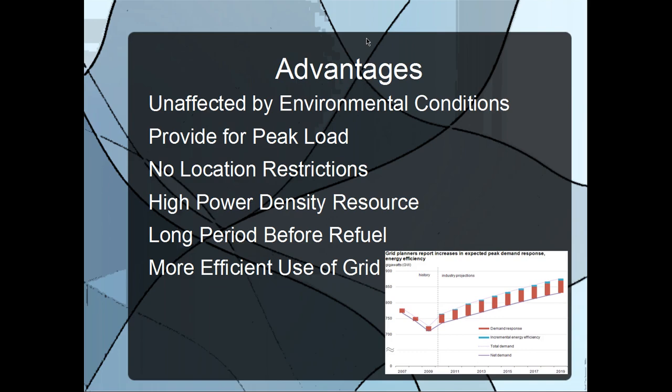Coal and natural gas plants need to be located near a primary source or have extensive support to provide continuous fueling. This is necessary due to the low electrical production value of coal and natural gas. For example, it takes about 1.05 pounds of coal to produce just 1 kilowatt hour of electrical power, and 1,000 cubic feet of natural gas to do the same. This means that the typical 500 megawatt coal and natural gas-fired plants use about 1.4 million tons of coal and 43,800,000 MMBTUs of natural gas per year, respectively.